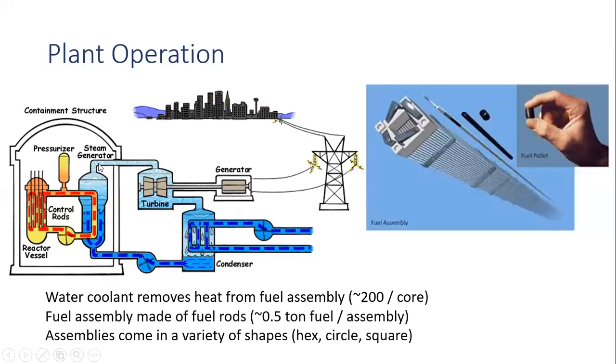When the steam is generated, by using that steam energy, the turbine blades are rotated. After the rotation of the turbine blades, which drive the generator, some amount of steam energy is given to the condenser, and this water again flows through the reactor vessel.